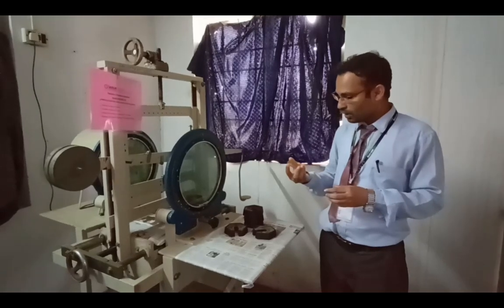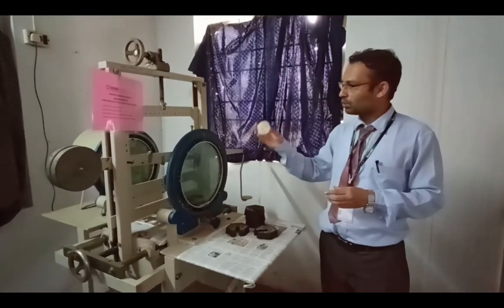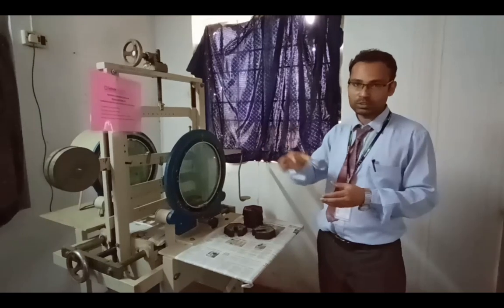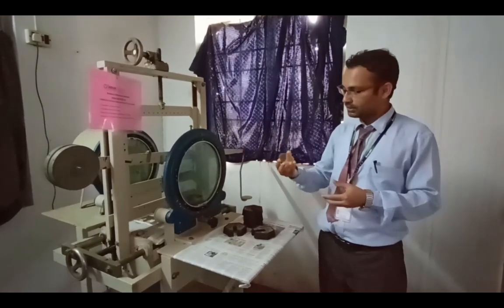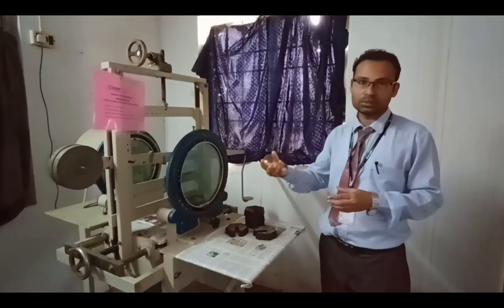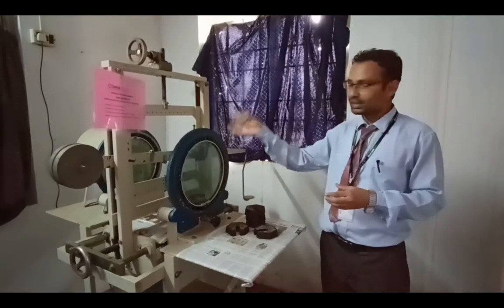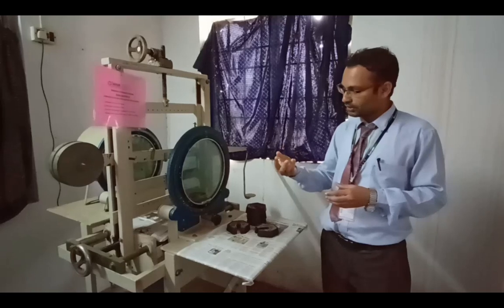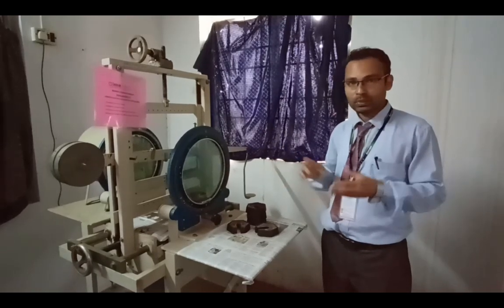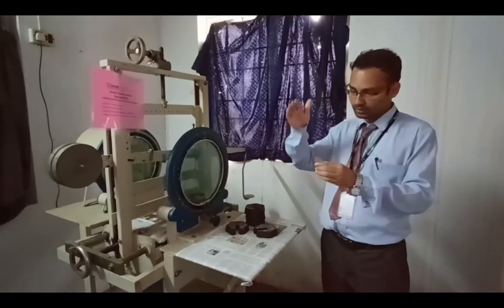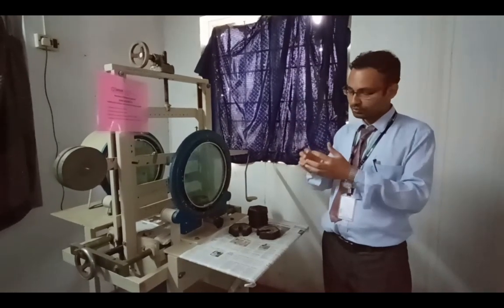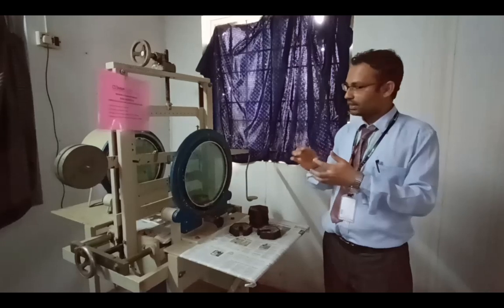Before going to this experiment, I already told you in the first part what is meant by photoelastic theory, what is meant by the circular polariscope, and what different types of specimens we are going to use to conduct this experiment. For your syllabus we are going to conduct two specimens. One is a circular disc, where we apply some compression force, and you need to take how many fringes occur in this element.